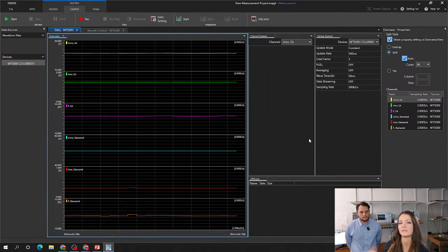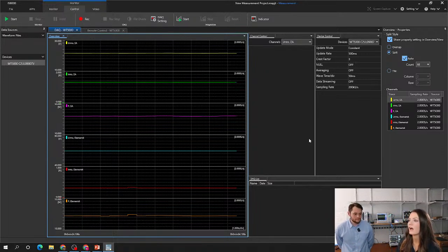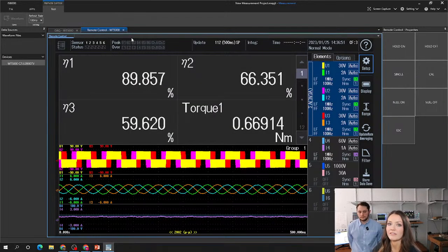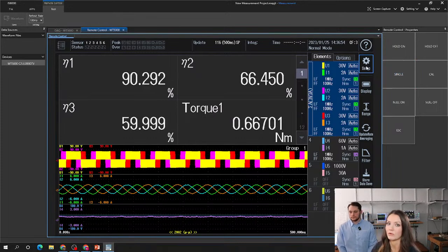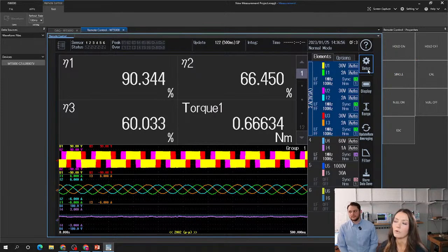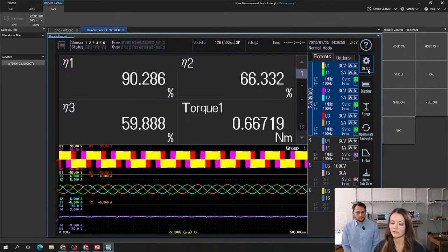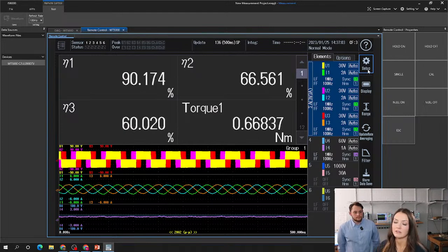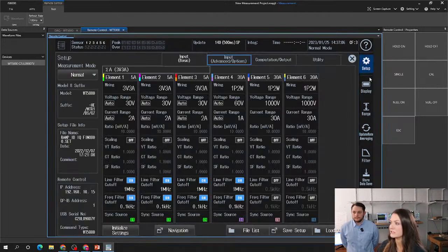And you can actually open this file once it's done recording. You can open it back up in IS8000 for analysis, or you could convert it to a CSV file to open up in Excel and look at the data there. You can also store the data on the 5000 to a USB, or you can use FTP to transfer the data from the 5000 to the computer without the software. So there's a lot of different options there. You can set it up to store for a while.